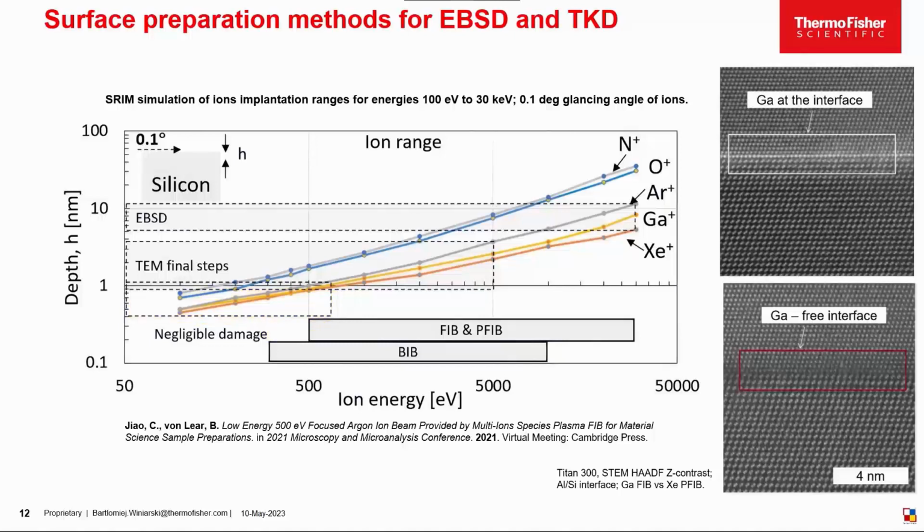Now, since argon and xenon are noble gases, the problem of nanoalloying and compound forming does not exist, while gallium is known for forming low temperature eutectics and can travel millimeters far along the grain boundaries in metals, for example in aluminium. The high-resolution TEM images show a gallium monolayer formed along the aluminum-silicon interface.